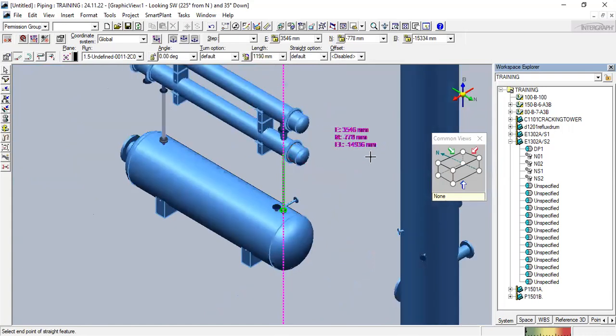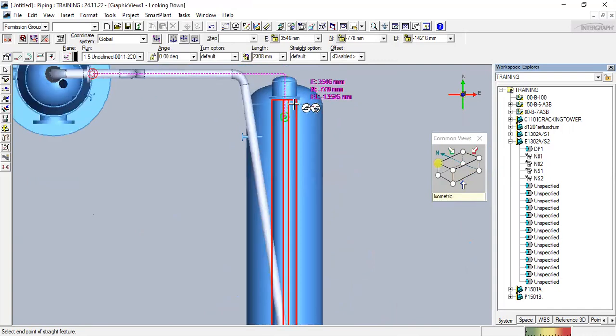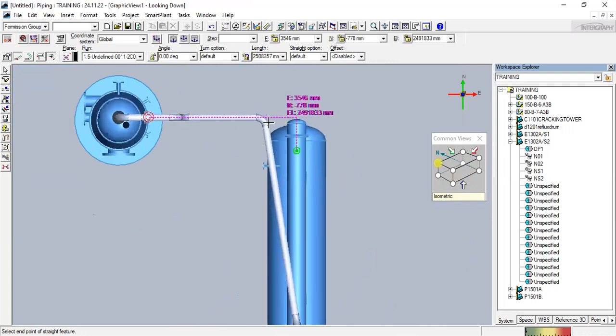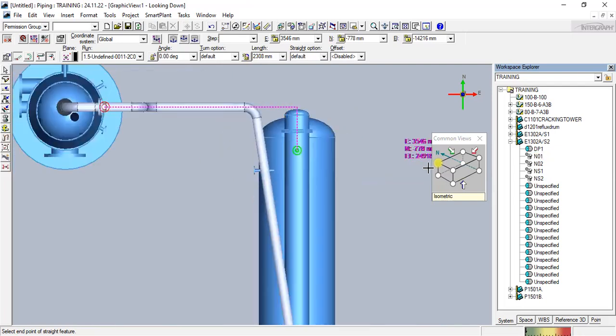Now see, you have to check the view from the top. See, this pipe is directly connected, which means it is wrong. I have to modify it again, because I did this in a quick route, right? So we have to modify this from here to here and then from here to here. So the quick route option will come, and it will vary from situation to situation. So now I need to focus on this line.